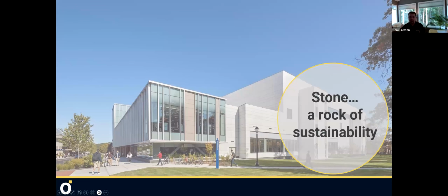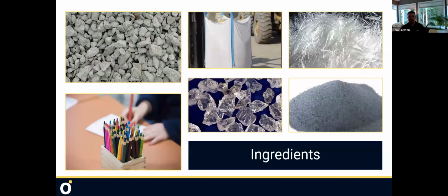So stone, why do we want stone? Because we don't want those problems, because we want to offer more. We want sustainable solutions that offer long warranties that stand by their materials. So how do you make an engineered stone rain screen panel? And Victor wanted to know what the difference is. Notice there is no cement in this panel. The Petrarch line has reconstituted marble. So it's marble, it's chopped fiberglass, it is some quartz, it is pigment, natural pigments, and then it is a resin base.